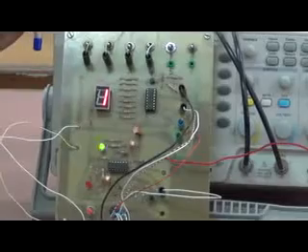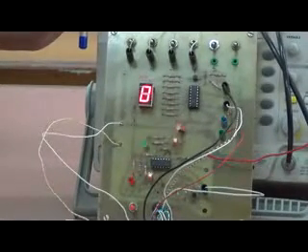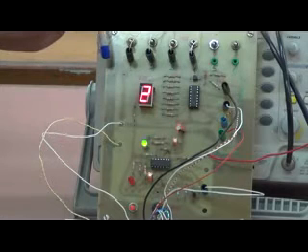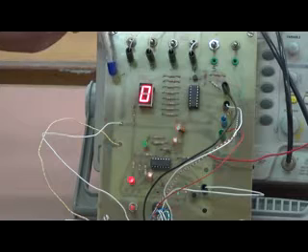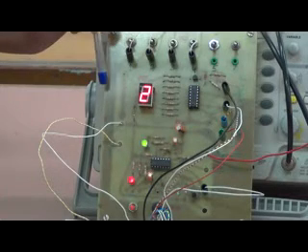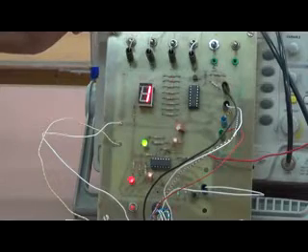So it's an up counter, and it keeps on repeating the same values 0, 1, 2, 0, 1, 2. Hence it's a counter that keeps on repeating a particular sequence. So the divide by 3 counter is observed on this digital test board.